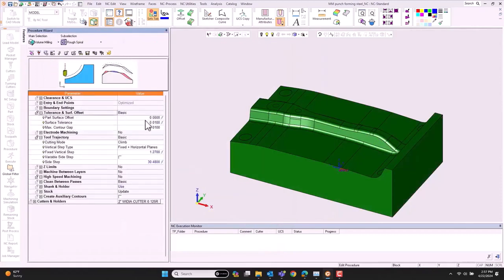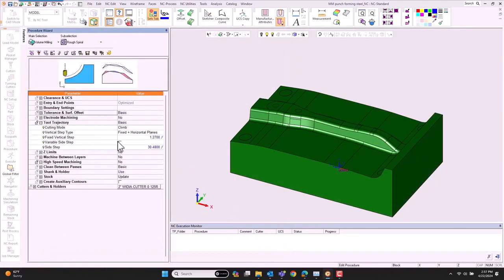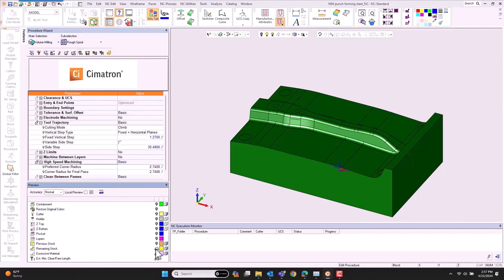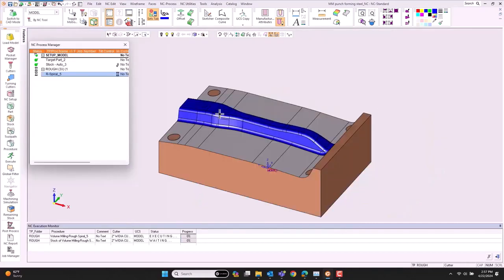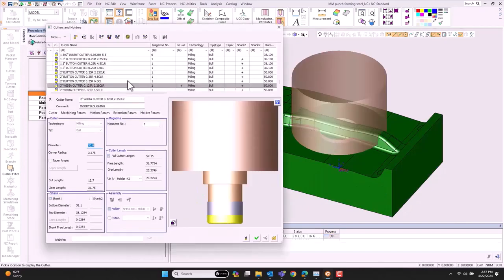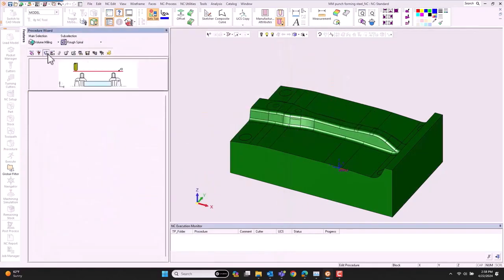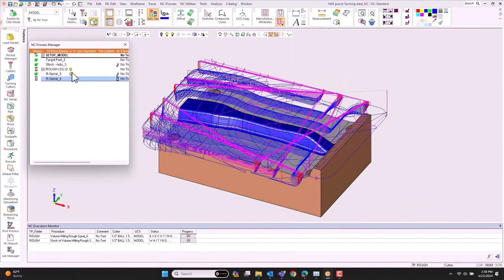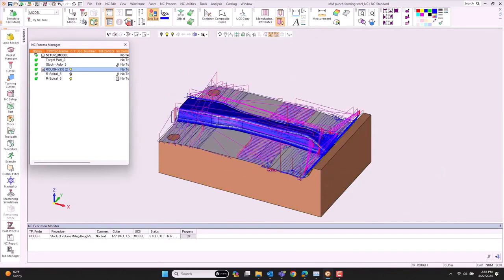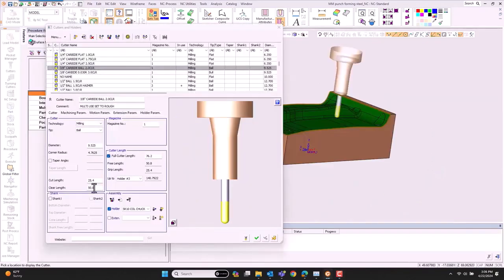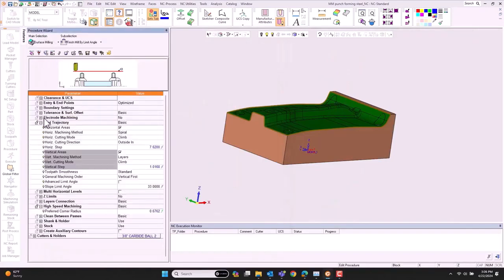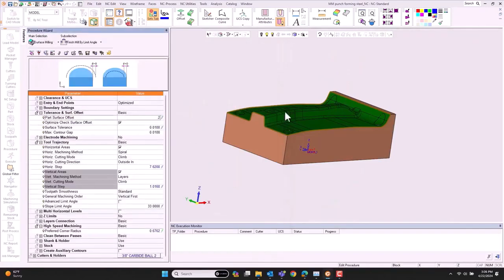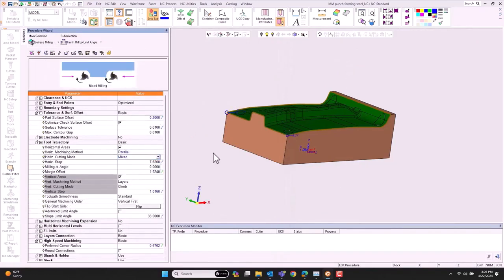Further along the way to go with this would be to do some NC. So here I've pulled in my tool library, and I'm working with one of those different form stations, setting up what I want for my offsets and my step overs. In this case, we're doing a rough cut, a rough spiral. And as we do it, it's going to know where the stock is, and it's going to target just that stock. So if I come back in here with another rough cut, it'll cut just that remaining stock. Also, it's a smart system. It knows where the holders are. It knows where the vise is. So all that can be identified and then avoided when it comes time to cut it.